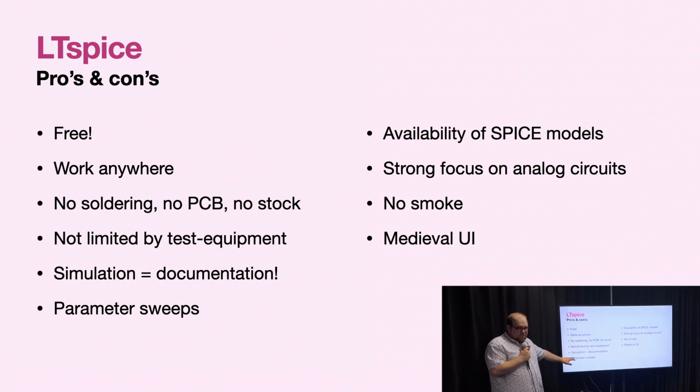And then it's also very easy to investigate how changes in certain components will affect the function of the circuit. Whereas with the breadboard, you have to physically plug and unplug components. With LTspice, it will automatically sweep through all kinds of combinations. Now, there are also a few significant disadvantages, and that's you can't always find the right models for every kind of component, which is a pain.